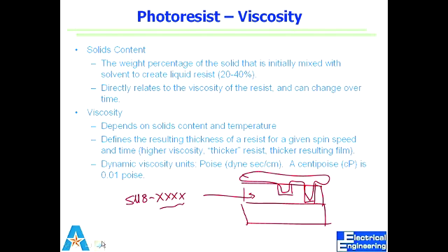So it's not that we have just picked a viscosity range and we are sticking to it. There's a reason why we want to stick to that thickness that we get out of that. We want to control the thickness that we make out of a specific resist, because above or below we won't be able to translate into a design.